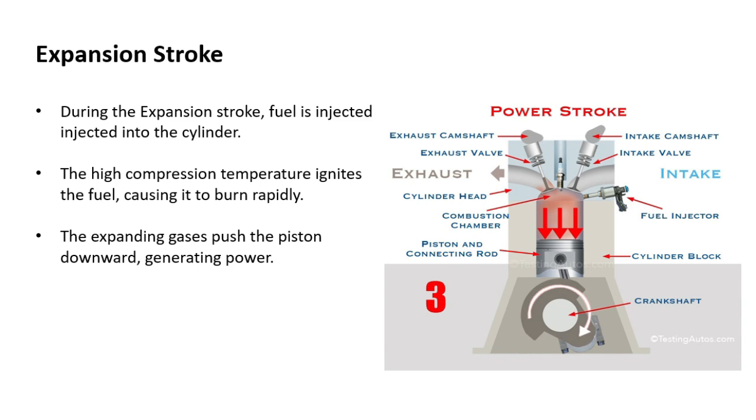Now, the combustion chamber is completely full of exhaust gas. We have burned all of the fuel, and what we have is a space full of exhaust gas. Now, we cannot just inject the fuel into the combustion space at this point because there is not enough oxygen within the combustion space for the fuel to combust. So we need to remove all of this exhaust gas from the combustion space.